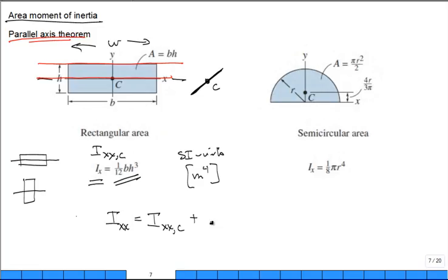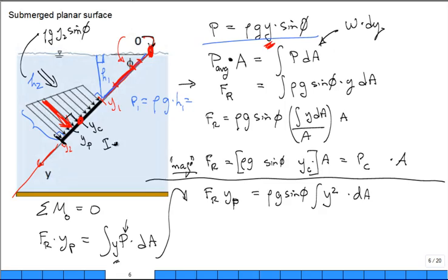So you can almost guess, but I'm going to let some people shine. I'm going to pause, walk around, and see how many people write down the parallel axis theorem, and this is the part that I'm missing. All right, so basically you have this axis. If I want to move it from this axis that goes through the centroid, it has to go through the centroid. You introduce a distance often called d. That's the distance between the two parallel axes, true? And so it's d squared times the area. It gives you your units. How many people now say, deja vu, got it? True? D squared A?